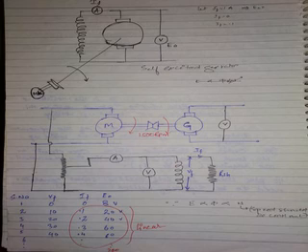Now imagine, theoretically, the resistance of the field winding is increased to 150 ohms. What will be the field resistance line? Will it go up, will it come down? Definitely it will go up, right? 150 means 150 by 1, the same 1 ampere point, and the voltage point will be at 150. So you have to join one more line. This is also the shunt field resistance line for RSH value 150 ohms.